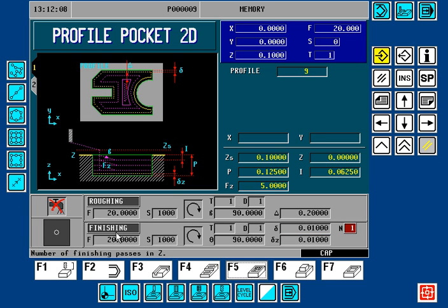When defining your finish pass, you define your tool number, your entry angle, the amount of material to be left on the sidewall and on the bottom of the pocket, and here you have to give it a number of how many depths of cuts on the sidewall here that you want to make for the finish pass. Up here you specify a depth and the increment depth for cut. But here, once the material's all been removed in roughing, how many sidewall passes do you want to take? Okay, you could take that in 1 or 2 or 3.